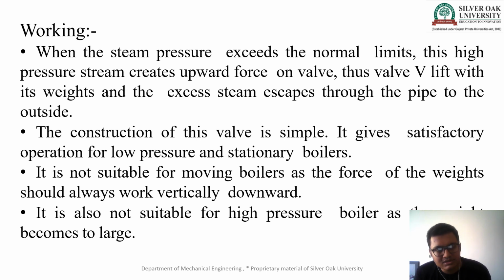The construction of this valve is simple. It gives satisfactory operation for low pressure and stationary boilers. It is not suitable for a moving boiler because when we move from one place to another, the balancing will get disturbed. Then the working pressure which we have fixed on the downward side will be changed.